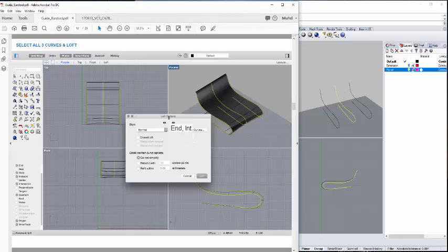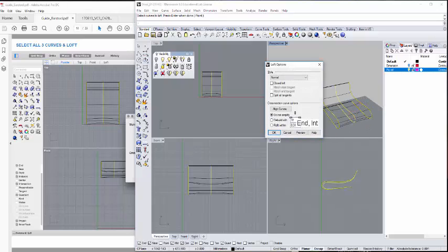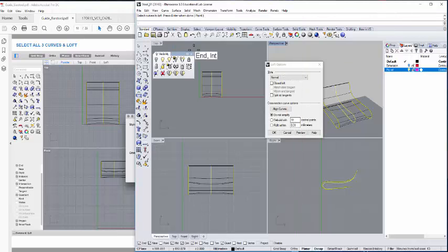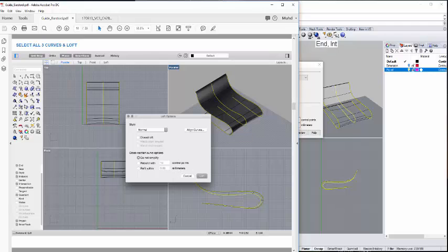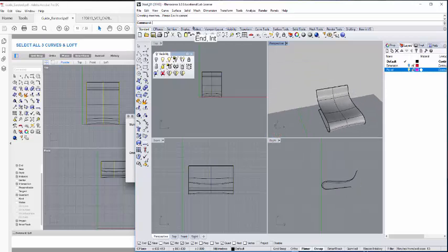Go down. I need to loft, select all three curves and loft. Do not simplify. Escape, loft. Okay, this is normal, do not simplify. Check normal, do not simplify. 10 by 0.00. Okay, preview. Change to shader mode. Yep, looks quite okay.